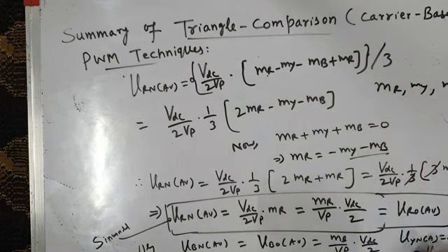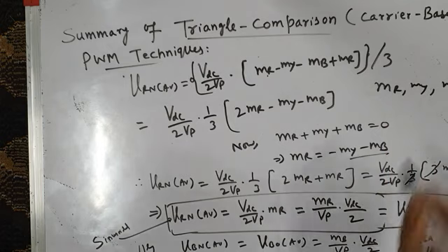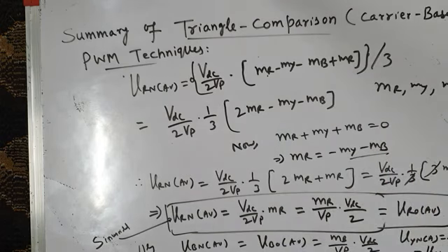We have proved that since the modulating waves are sinusoidal, the pole voltages, the line voltages, as well as the phase voltages are also sinusoidal in nature.